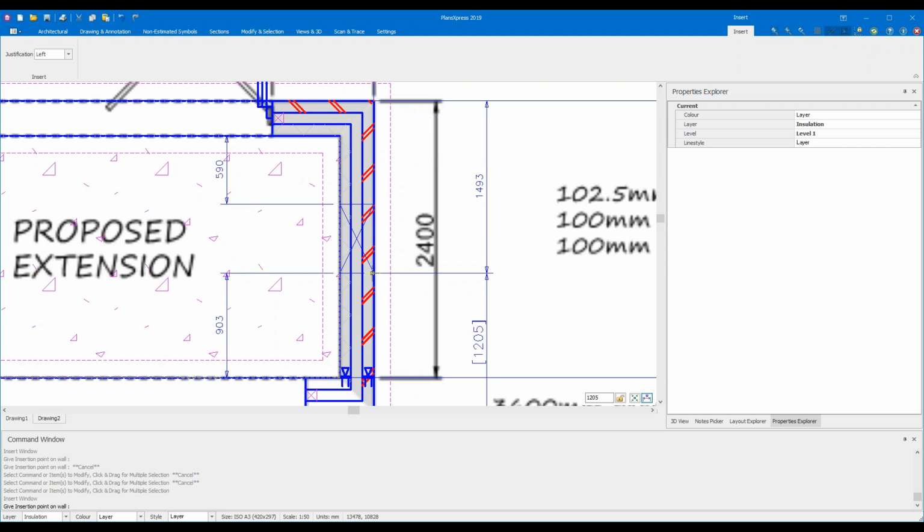Okay. There are a couple of different keys that you need to use to place a window correctly using the measurements. The first one is your tab key. So if I press the tab key, you'll see the dimension in square brackets changes. The other thing that dictates where the dimension in brackets appears is the cursor position. So if I put my cursor over the internal leaf, that dimension in brackets, which we call the active dimension, is measuring from the inside.